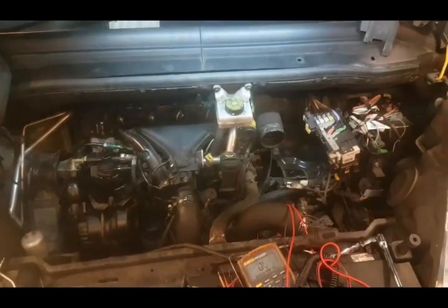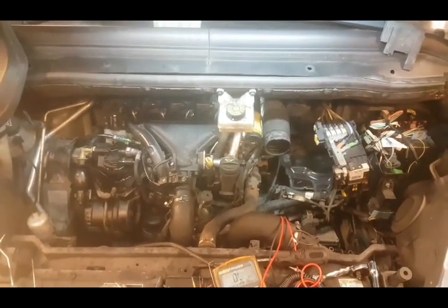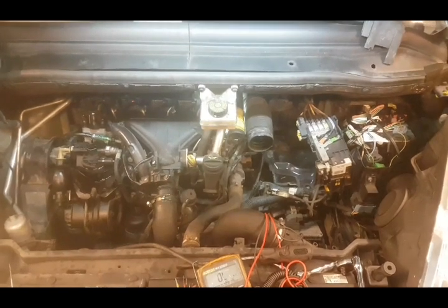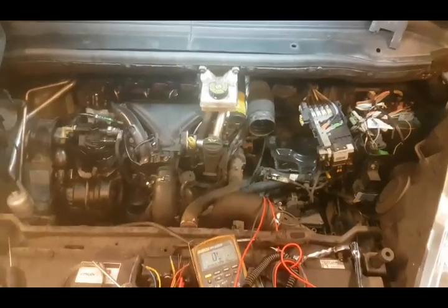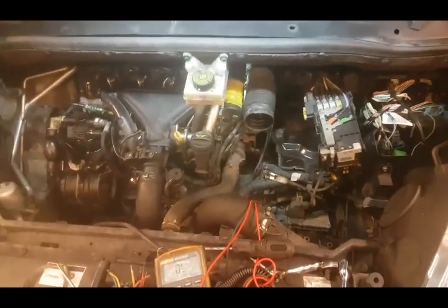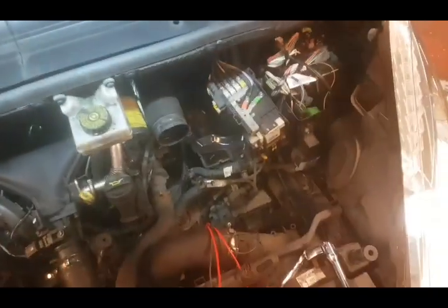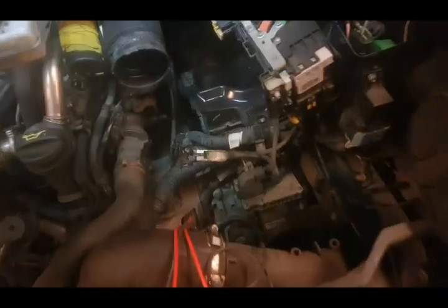So, due to the fact that we have low fuel pressure on cranking, but once fired up we have plenty of fuel pressure, I think we have something sticking slightly open, so a good bet is to go and inspect the fuel pressure control solenoid. To do that, you've got to take the battery out. To do that, honestly, it takes about half an hour. Just take the fucking battery out.